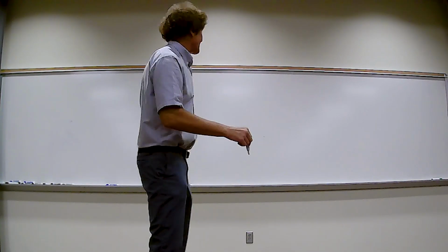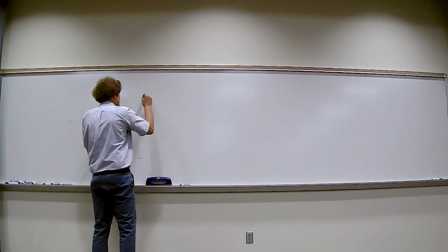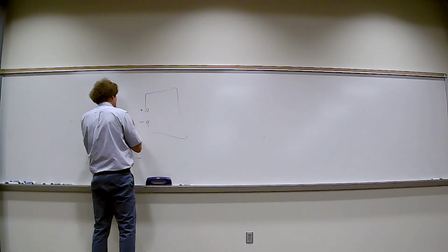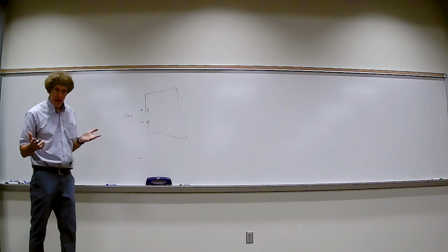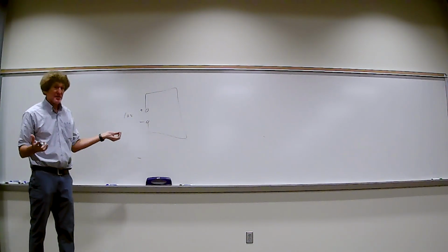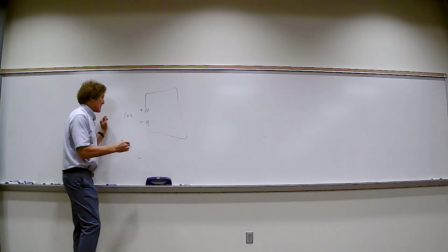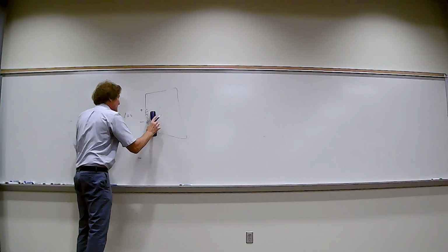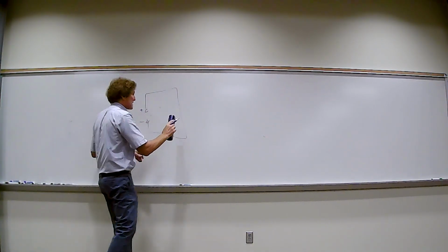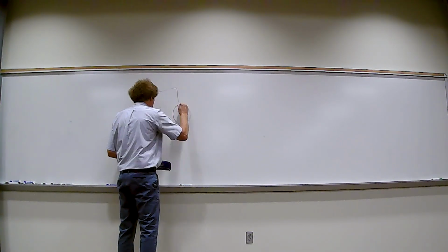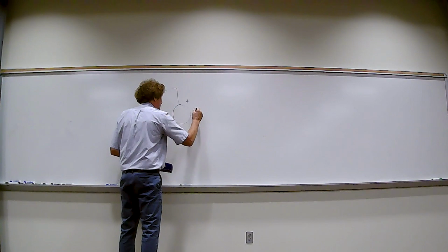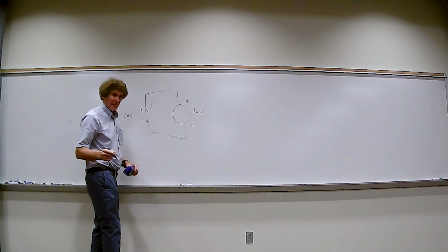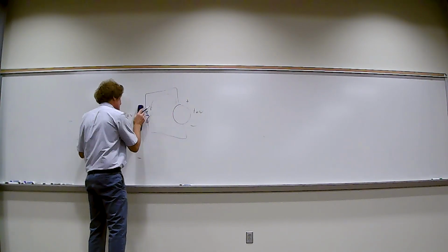Just go with me on this one. Don't worry about the B field, but suppose I get plus to minus 10 volts there. We know there's going to be a resistor there, right? Well, you don't put a plus-minus 10 volt source here because current would go this way. If you want something that replicates this behavior, you put a voltage source here that will be plus to minus 10 volts. Now, if you break that wire, it will get 10 volts. You all see that? And then you put your resistor in there. There's 10 volts across it.